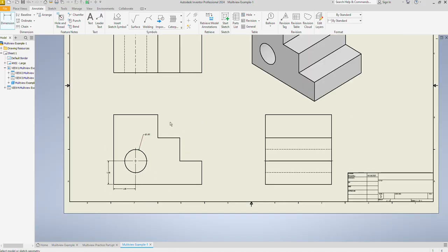The next one is the steps. All right, you can use the general dimension here, and like we said with the circle, if you want this whole line, make sure when you click it, it's just the red line, not that center point or the midpoint where it has a snap. Because again, if you go from there, it's going to measure from there, which is not what we want. That's the halfway point, not the whole line.